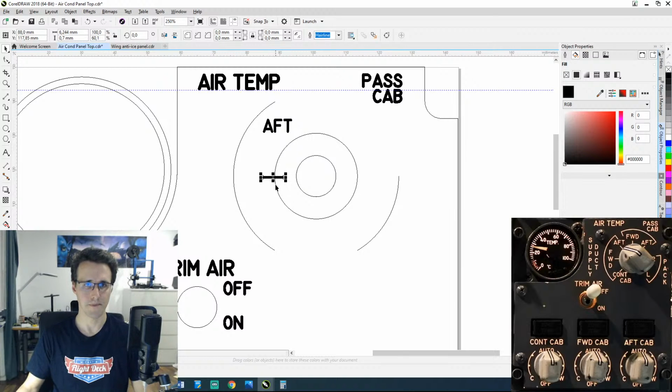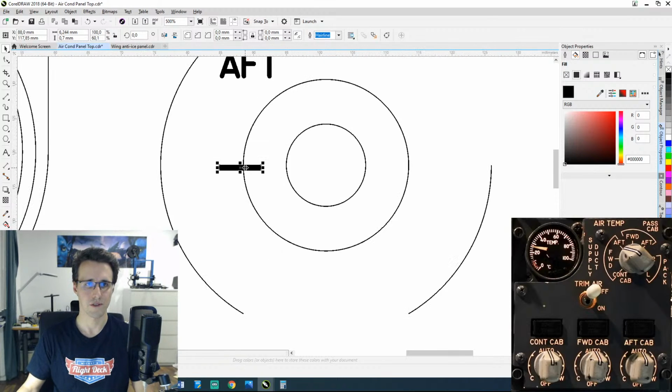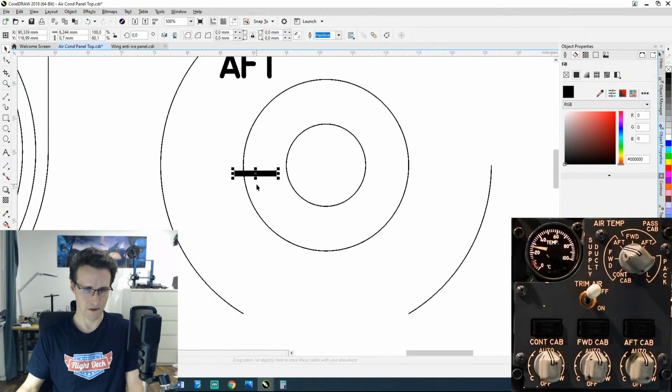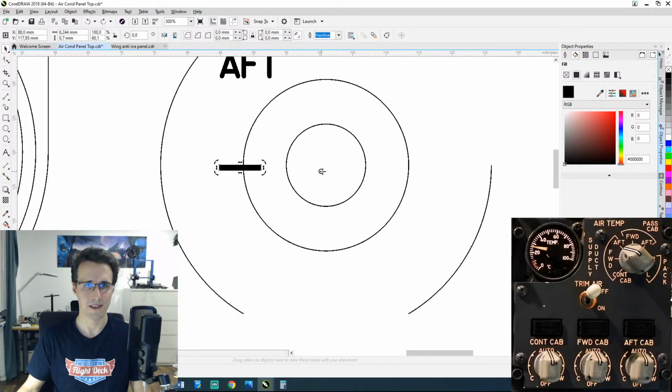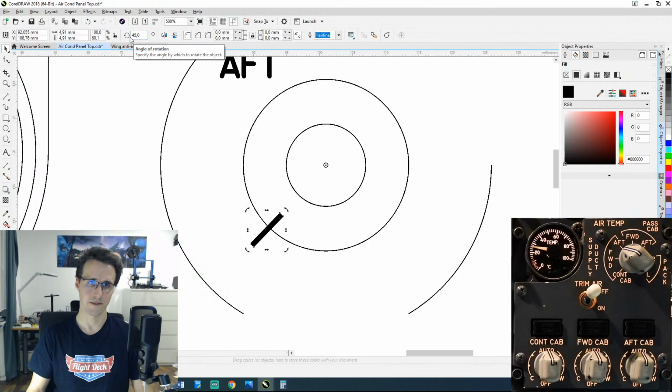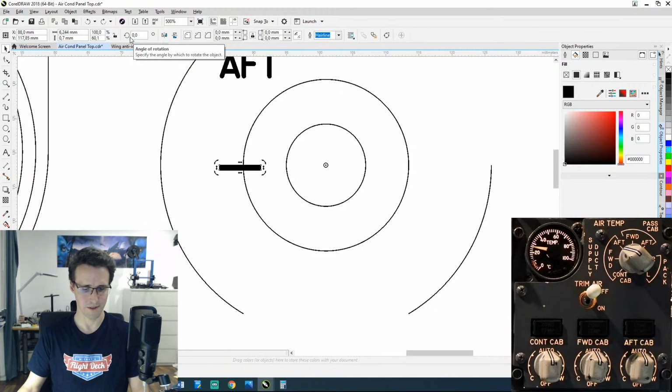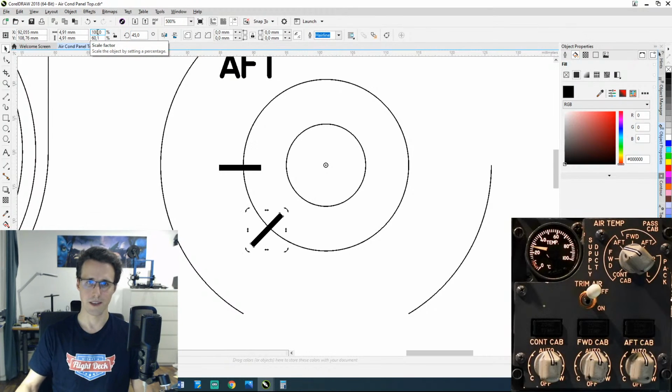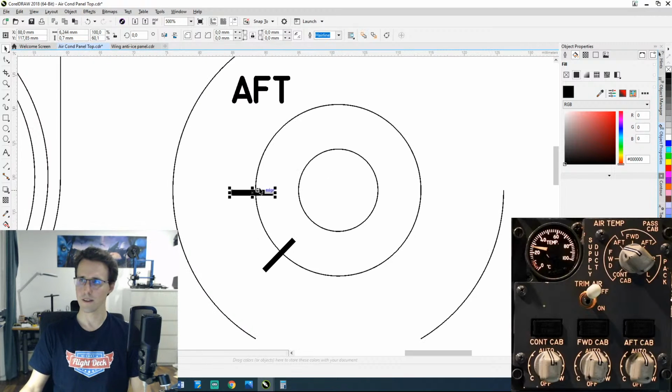We want to make a copy and turn it and rotate it, right? Not move it. So now we are in the rotating mode, and we can adjust the center, not center of gravity, the pivot point. It's called the pivot point. And rotate it 45. Yes, okay, but we should make a copy first and then rotate it 45. Yes, and that's where I want it to be. So another one.